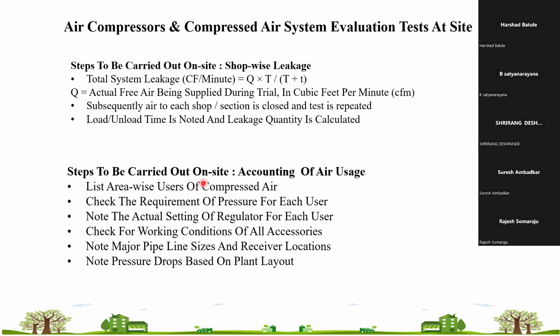And from that FAD, you can calculate the actual specific energy consumption. You can measure your power. Let's say there is a 100 CFM compressor and an 11 kilowatt or 15 kilowatt motor. For better calculation, we take 15 divided by 100.